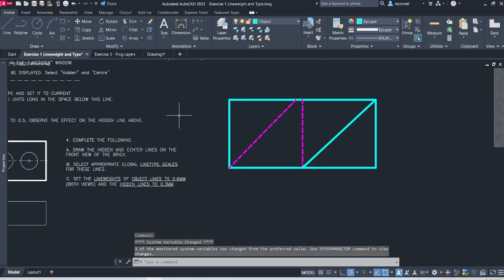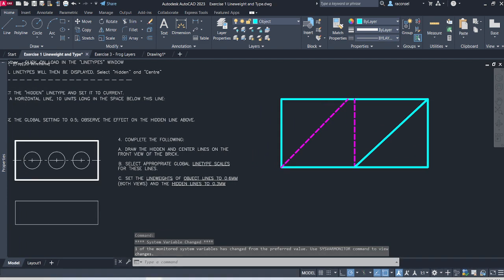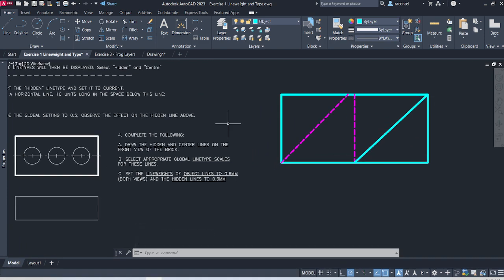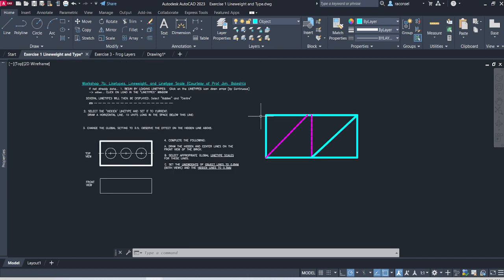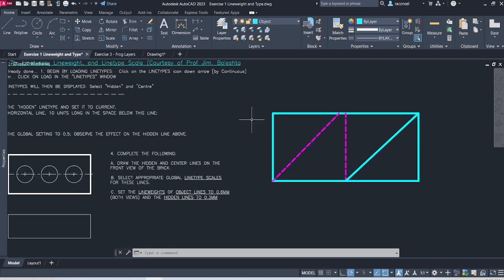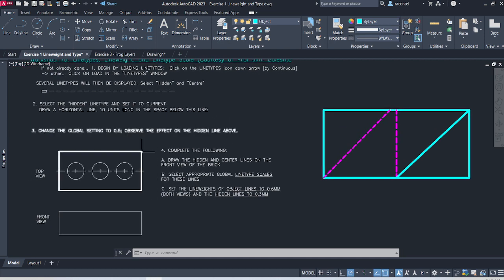So this is an interesting question. What is the normal color? Everything is printed in black ink on white paper. There are ways in AutoCAD to tell it not to print in color, to say, hey, all of these colors are actually black, they're just there so we can visually distinguish on the screen. So if we're looking at it in AutoCAD, it's a rainbow, but if it's on paper, it's black and white. We're not going to get into that. So all of your drawings should just be in black and white. You really shouldn't be changing the color, but you should know how.